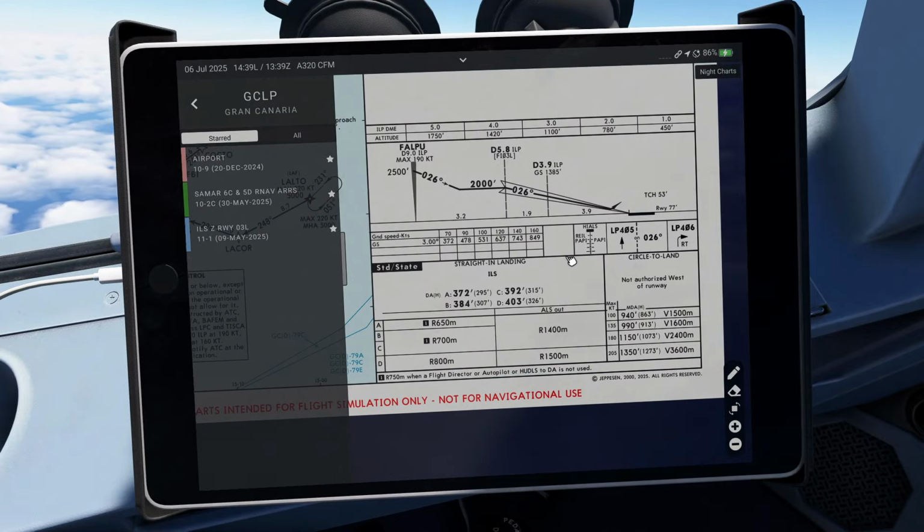It is about 9 miles from the runway threshold. From 9 miles to the active runway, you should be at full configuration, with your landing configuration set and your landing checklist done.